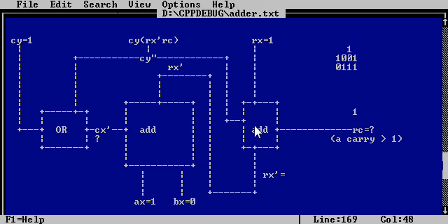So there's a 1 feeding into this adder. So we have 1 here plus 1. And that result of 1 plus 1 is 0, plus a carry. This goes into the OR. So it turns into an OR. And then I get a carry. So I got a 0 result and a carry. That's what I expected. That's what I want. So therefore the 0, 1 case works.